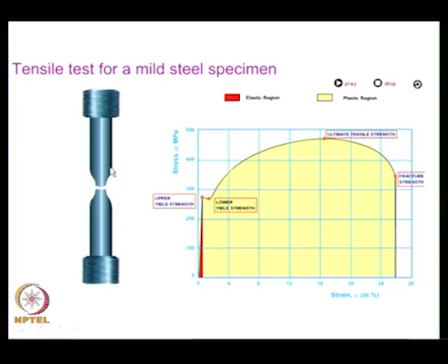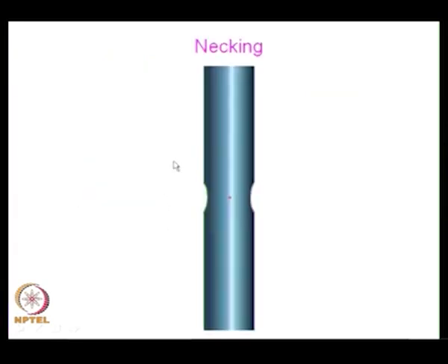There is a very simple model that I am going to show, and in the case of necking, it is actually the internal flaw which dictates along the length of the specimen where the necking would start. And what happens is, you have an internal flaw which precipitates necking, and this flaw grows in size. That is what you see here, shown in red,